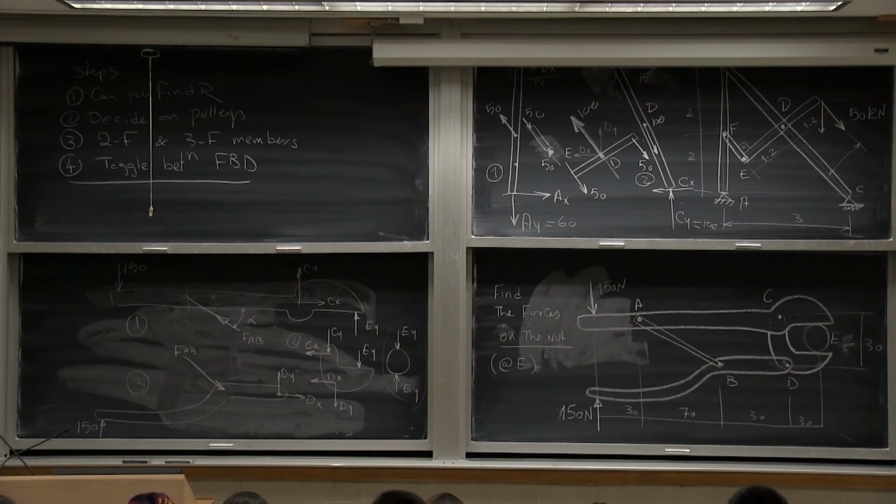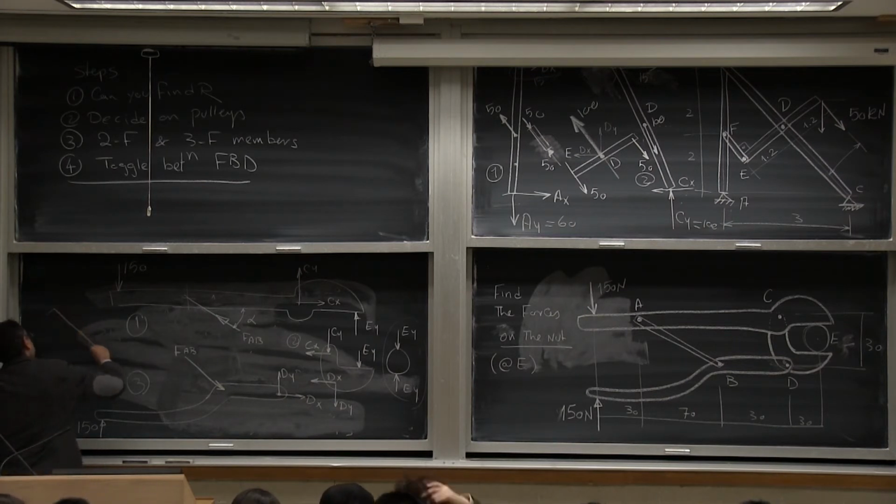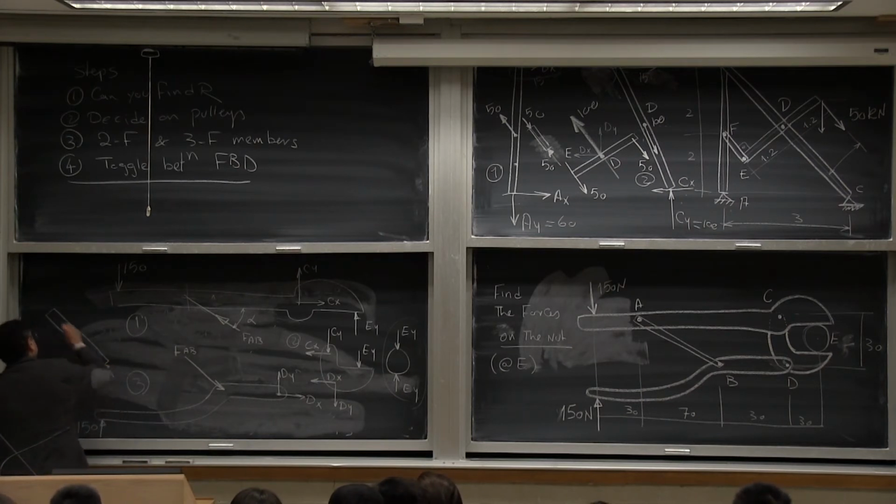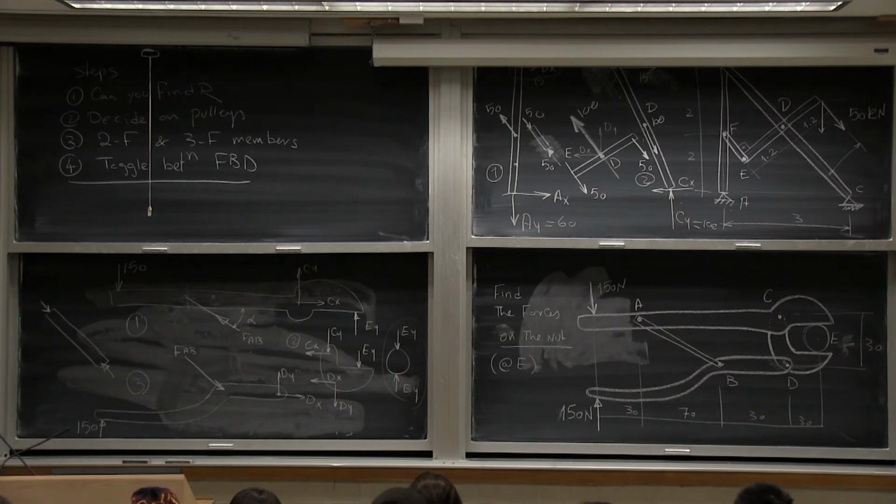The big mistake that I did here is that I did not draw AB. That's the bigger mistake, which is what is the member that is remaining, which is AB. Once you do this, you'll see there is a force here, a force here. I'm doing this, then this is in compression, and as such, it's pushing the other way.